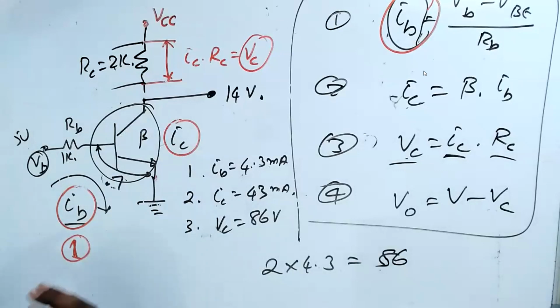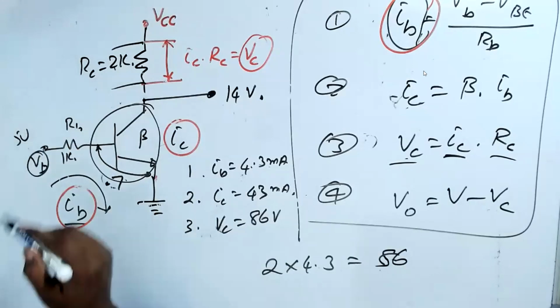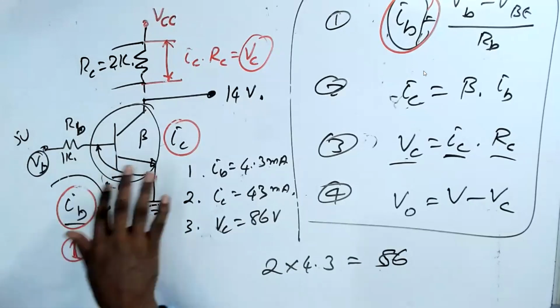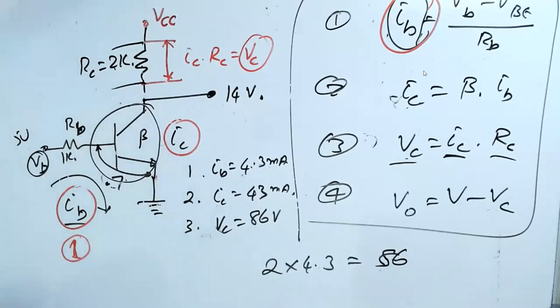The silicon diode is the thing that has 0.7 volt. You cannot add a resistor or anything there. That's why we are adding RB here. You can change RB. If you change RB, IB will change as per Ohm's law. But you cannot change VBE. VBE is always 0.7, which you cannot change. That is basically the behavior of the transistor.